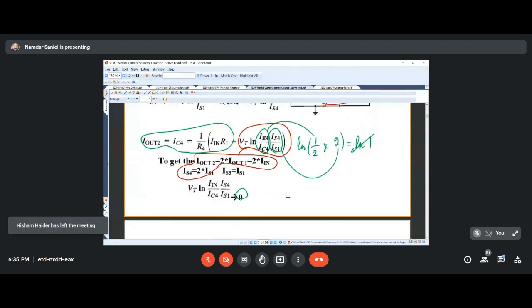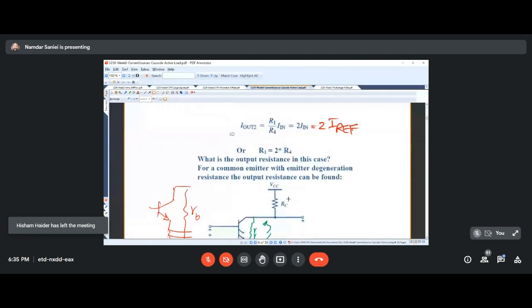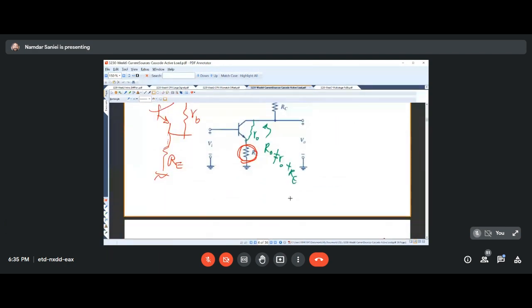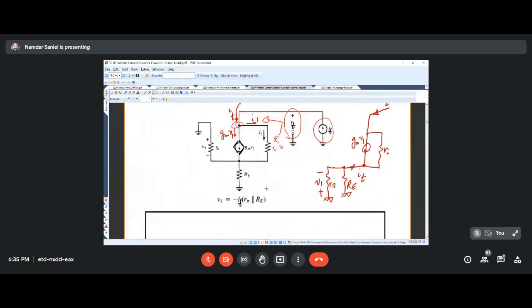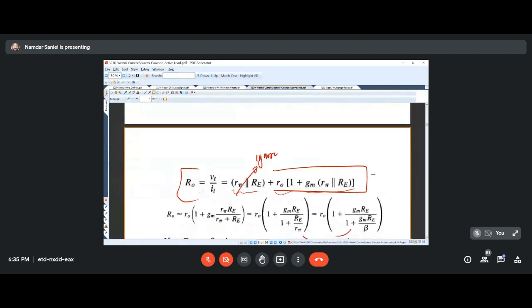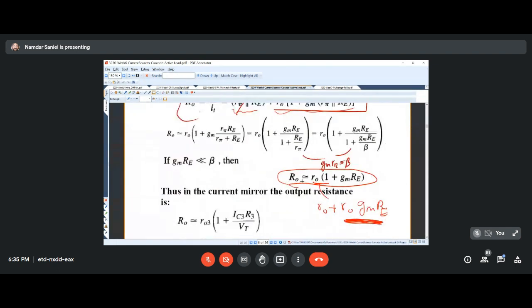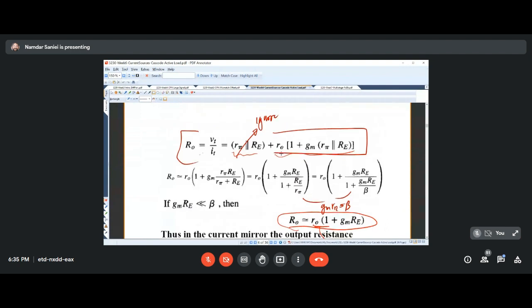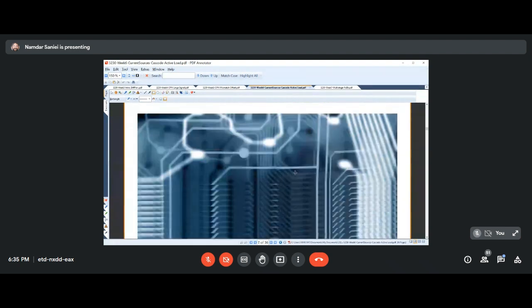And when we looked at it, especially in terms of the output resistance, we realized that it could give us a lot more larger resistance. And this was basically not only RO, but also a multiple of ROs added to that. So this is also another good equation if you want to write it in your formula sheet.